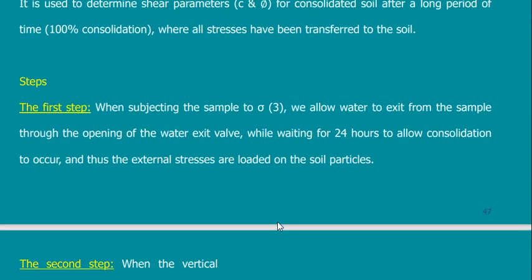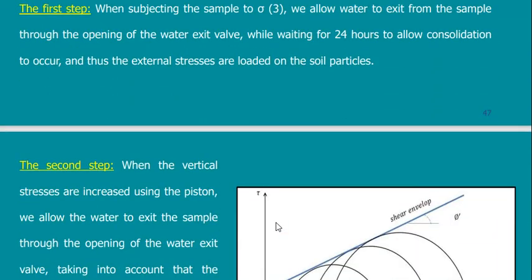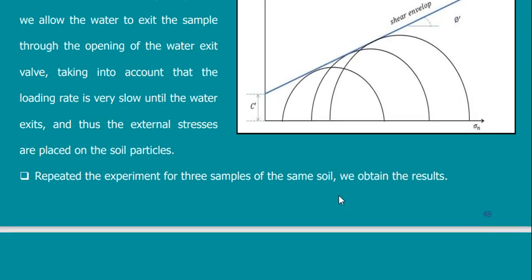Why? Because I expelled more water from the sample, and the soil now is ready to carry more. The soil is completely carrying everything, not the water contributing in carrying part of the load, and we said that water cannot carry shear. So now if water is expelled, then the sample can carry everything.